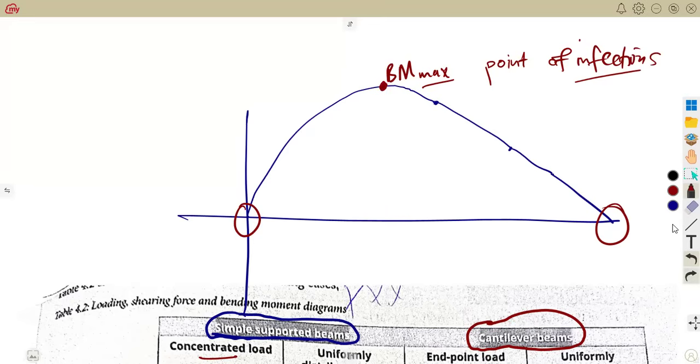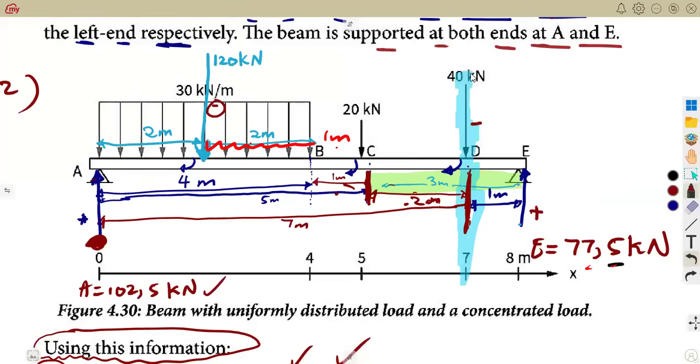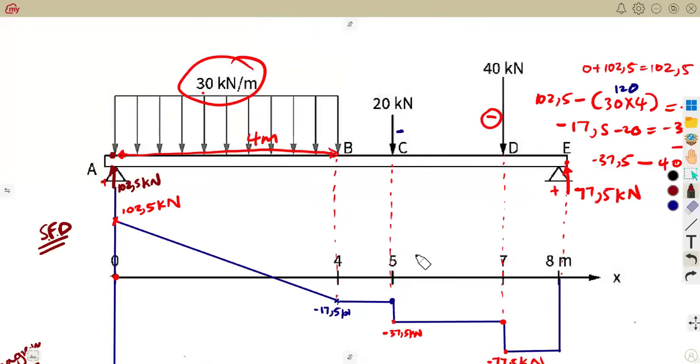This one, guys, you must be careful. You must consider according to the question, but it occurs on a condition of our question. It is going to occur from our shear force diagram. You see where we have this distributed load when it crosses our x-axis here, where it cuts the x-axis. That is where the maximum bending moment occurs. It occurs at this point.